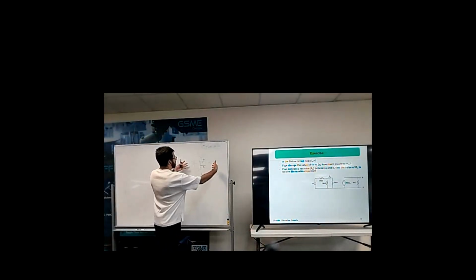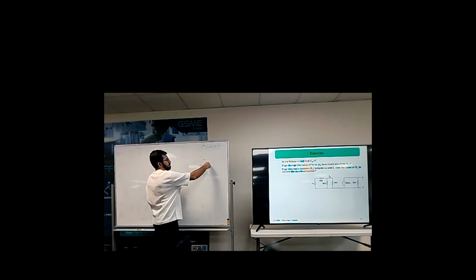When you connect a circuit, it should be a kind of loop. The current should be in a loop. If you don't have a loop, you don't have any current. So this current is zero. Why? If you consider a cut set here or here, there is no way for the current to come back. If current is going that way, there should be another path for it to come back this way, which we don't have.